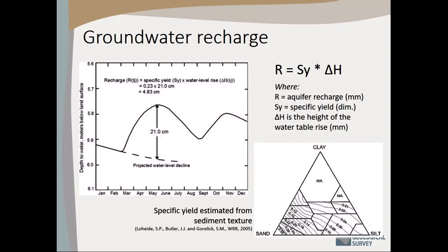So this 0.04 might be essentially saying that 96% of that soil profile might be filled with water. We only need 4% essentially added water to cause that jump in the water table. Not sure how clear I'm being, but these values are much lower than what you'd see in a typical soil science textbook because of that.